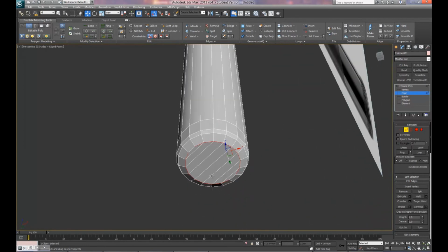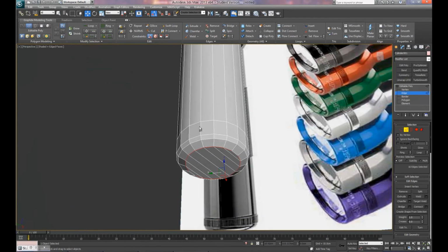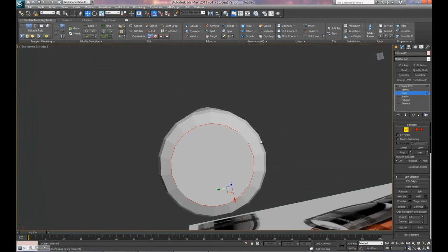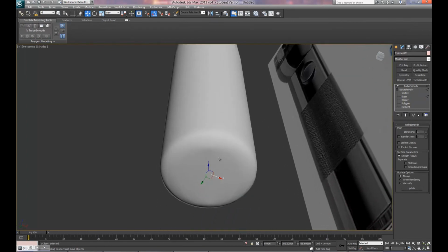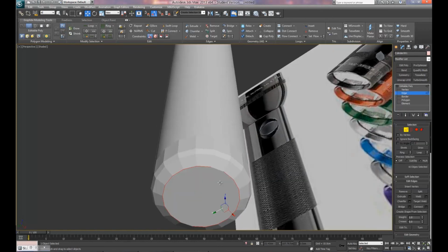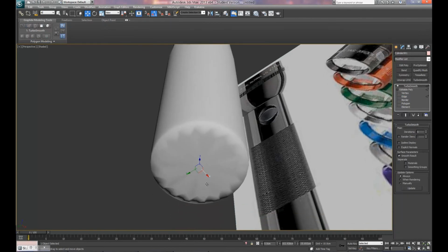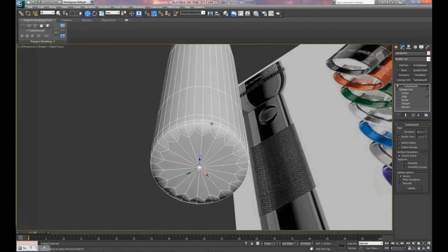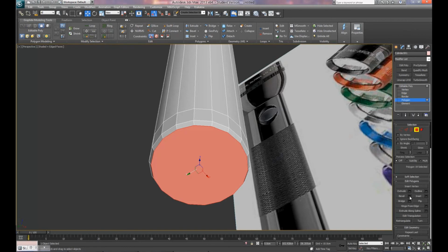And this is actually really important later on when we're making our high poly, when we finally turbo smooth this. And let me show you why. If we turbo smooth it now, you can see that it looks very clean. I mean, there's maybe a little bit of issue there, but let's say we were going to leave it how it was. You turbo smooth it, you get some hardcore flowering right there, and it's not an efficient way to go about doing things. So let me go back to where I was.